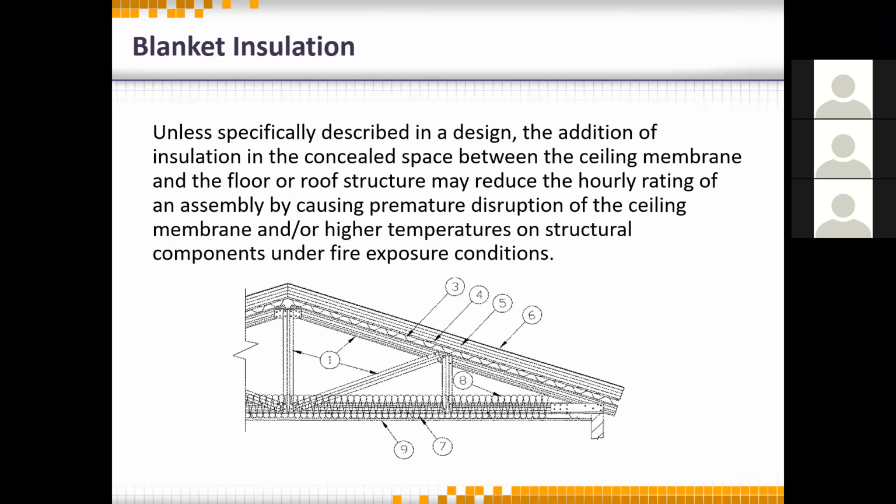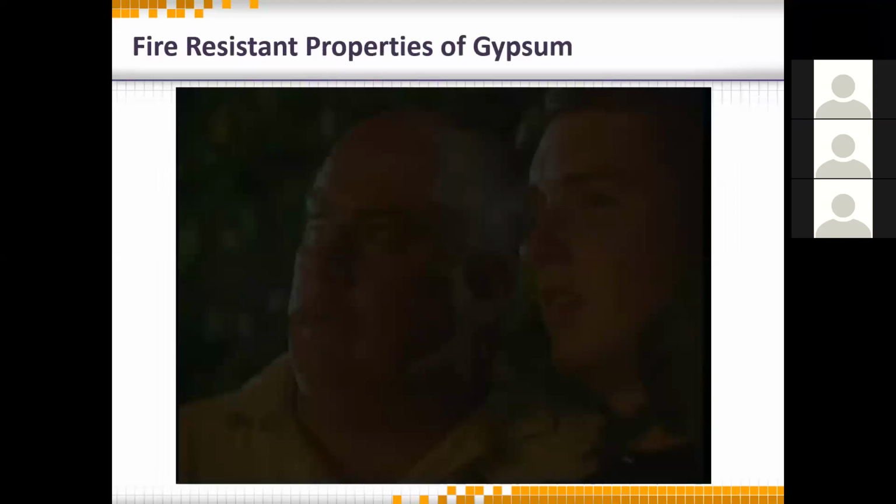The wall is, go ahead, add the glass faced or unfaced batt insulation to a wall. You get better STCs, obviously R value, so you can do that. Nothing additional needed to be done. But with these particular assemblies, you do need to add an additional layer of drywall to the ceiling. Quick video to give you a visual of that.